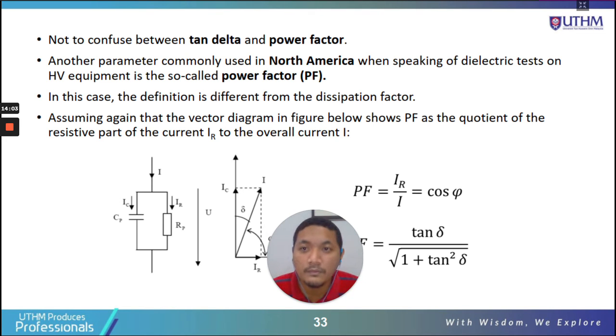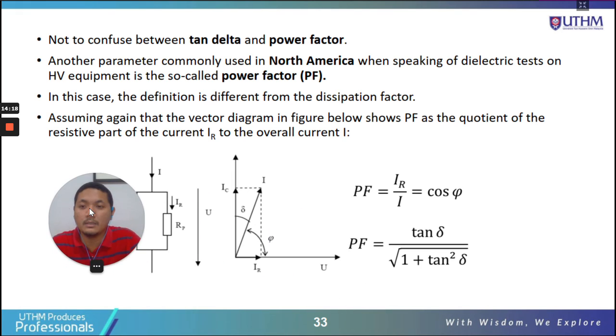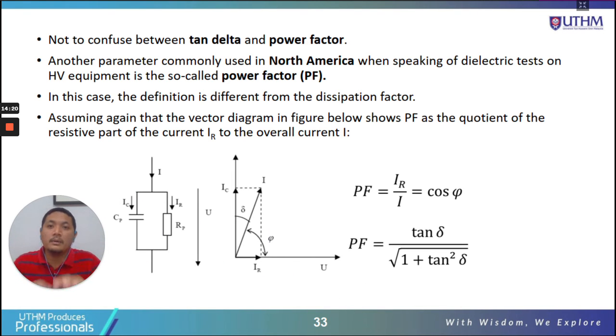So as not to confuse tan delta and power factor, these two terms are also commonly used. You have definitely come across power factor before. In terms of tan delta or power factor in electrical tests on insulation, power factor is usually used in North America.